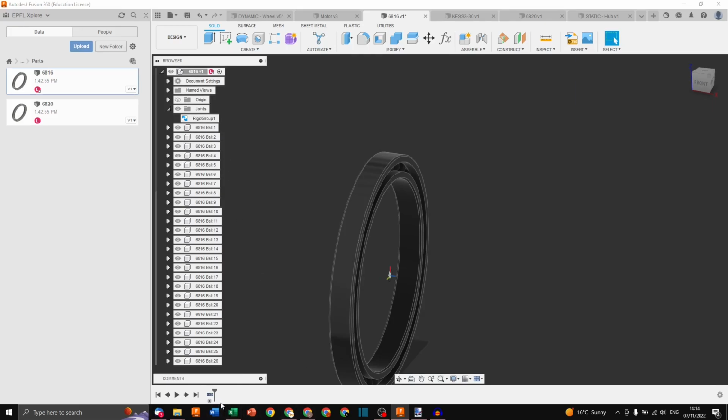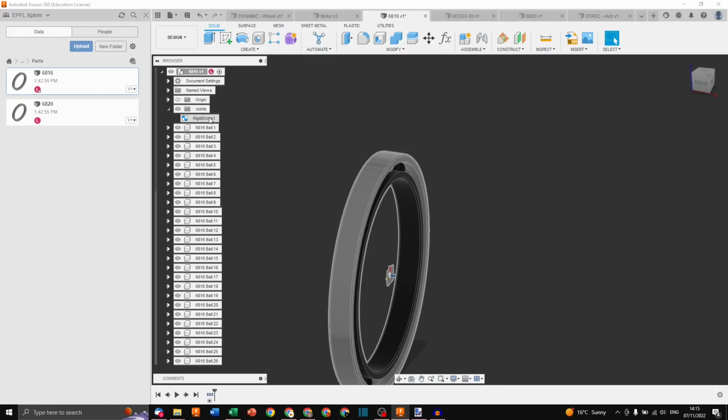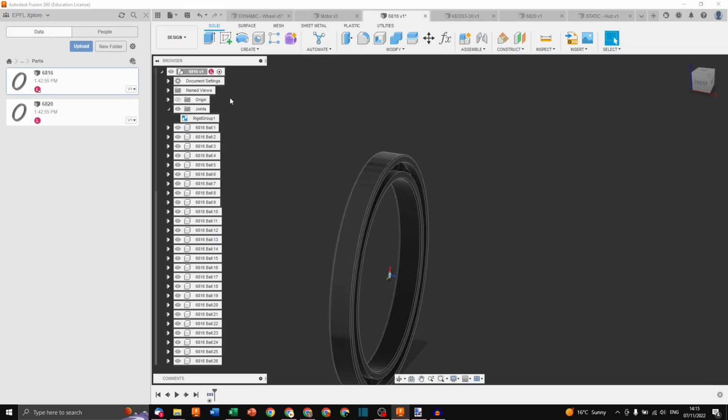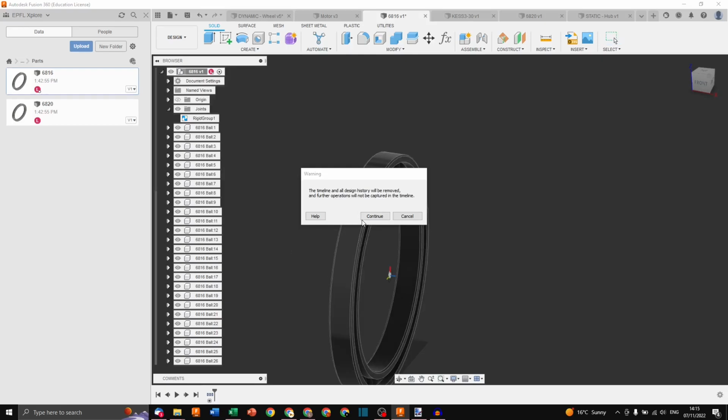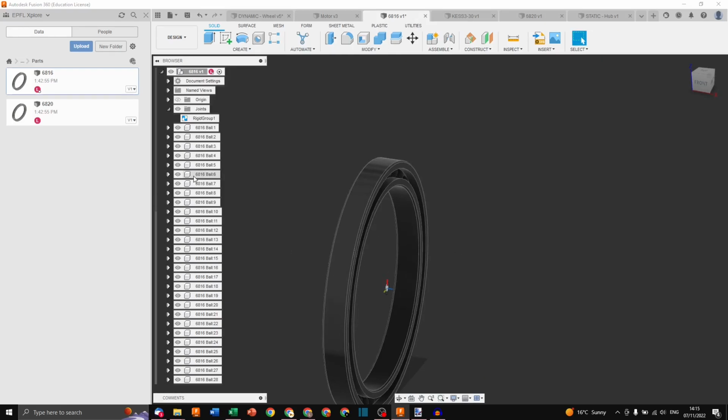The reason why it's not there is because the file is much lighter for Fusion 360 to handle if you do not have a huge history, because it has to recompute everything every time. It's much lighter for it to not have a history. So if you want to have models that you can easily work with, and you do not absolutely need a history, because you just do small improvements on a design, like add a rigid group or add a joint origin, you shouldn't put one. So I'll turn it off. Continue. This will make it lighter.